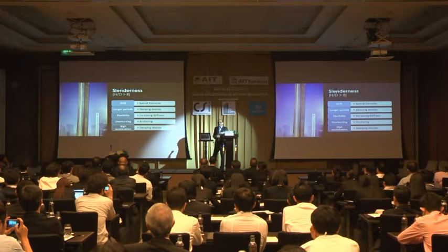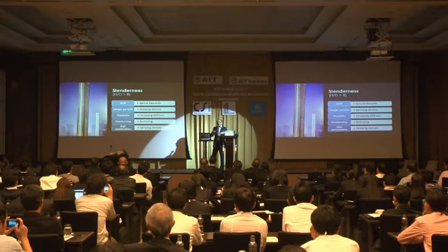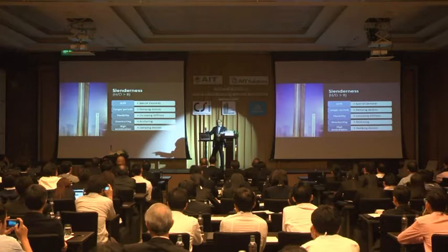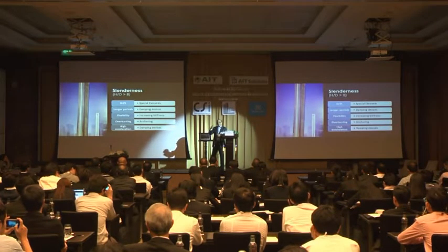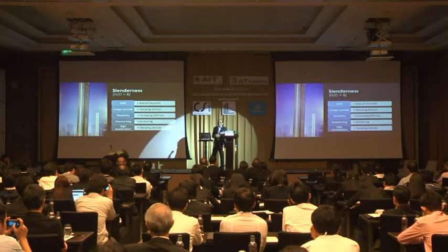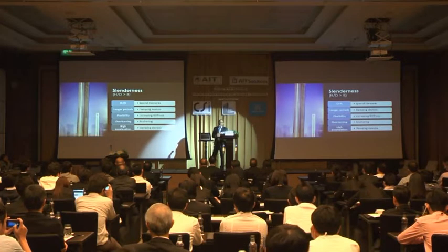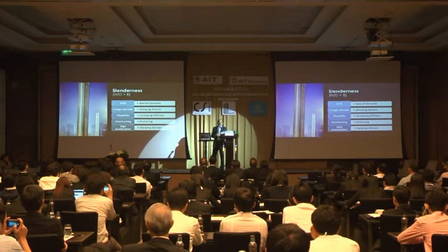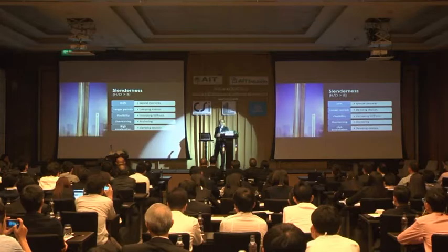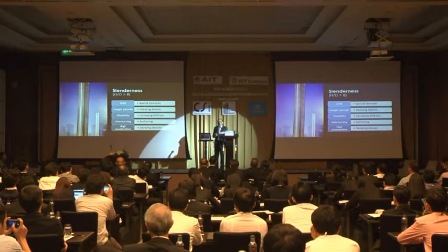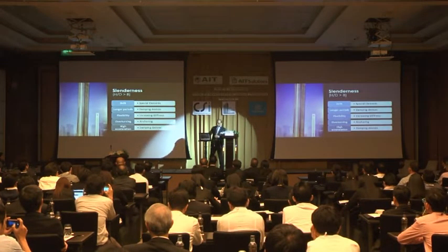Drift is a concern that links to many things, because drift links to non-structural damage, to facade damage. So drift is one of the key criteria to control, and slenderness leads to larger drifts. And thanks to our elevator friends, if there are no cores, the drift is going to be the biggest problem we are going to have, because so far the drift is being controlled a lot by the core walls. And if you have smaller cores or no cores, then I don't know how we will control the drift.